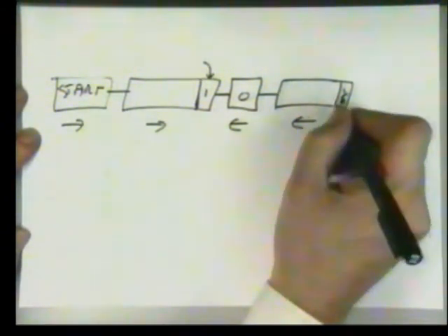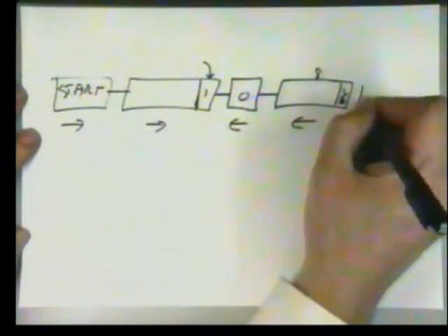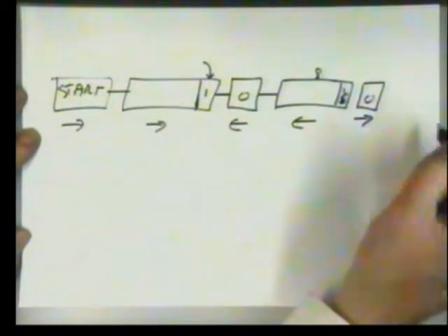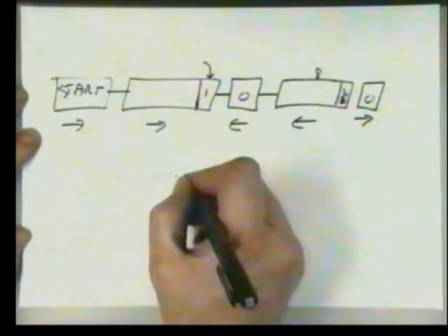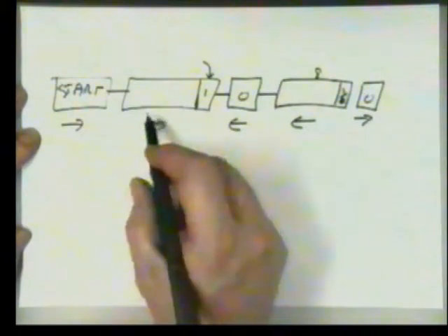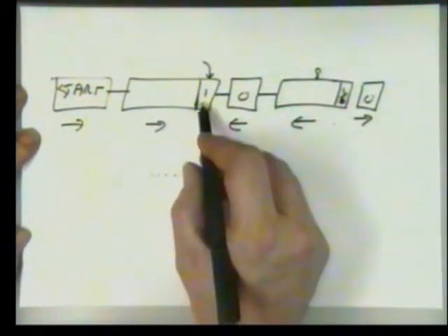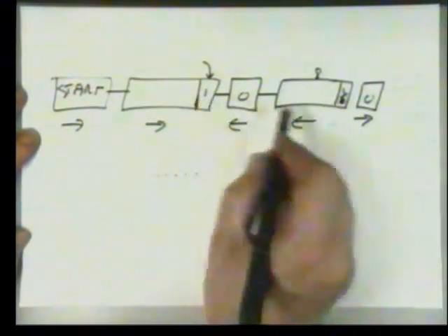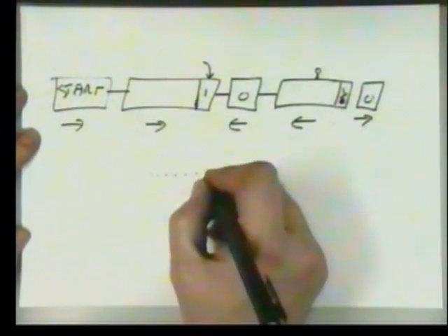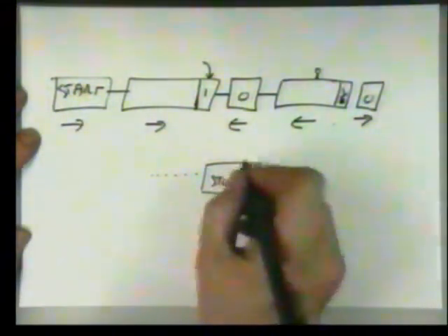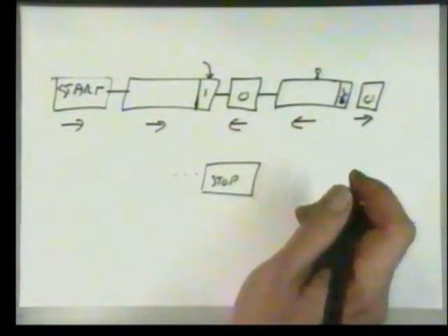Because the slave has now transmitted 8 bits, it's the master's turn to acknowledge what has happened. And so this can continue with a byte followed by an acknowledgement, byte by acknowledgement, with the direction determined by the least significant bit, and finally everything is closed down by the issuing of a single stop bit.